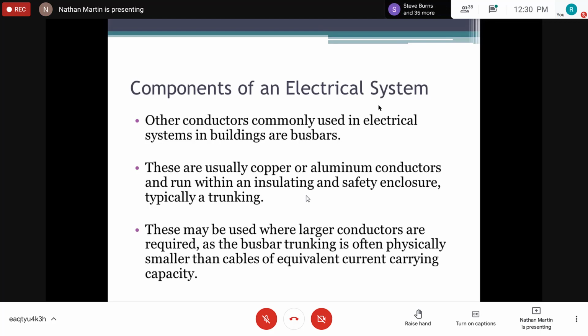There are several applications. In an industrial setting, you'd have a bus bar chamber, right? And then all the different sub-circuits are connected to that bus bar chamber through a breaker, right? So we're talking about large utility rooms, built from metal enclosures, right? A lot of these bus bar chambers are built to specification.